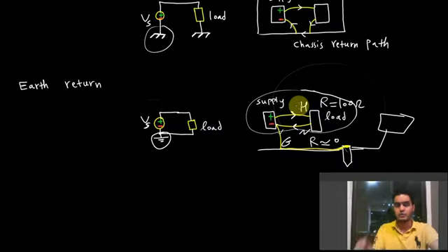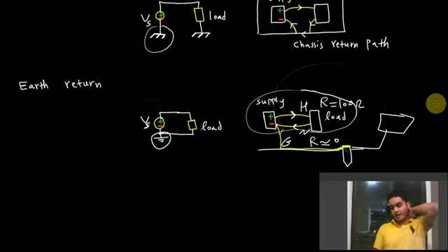You can see a trace is blown. But in a lot of cases, you may not be able to see any damage, and you would have a complicated circuit. You have no idea, okay, is this component failing? Is this component failing due to ESD? So electronic companies, including mine, have a lot of precautions and a lot of processes to avoid electrostatic discharge, and you have to follow those.